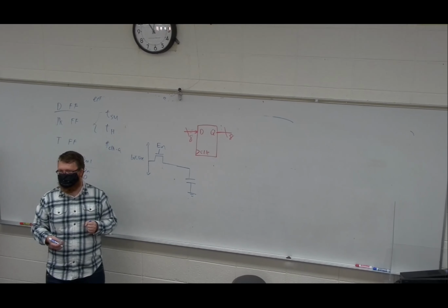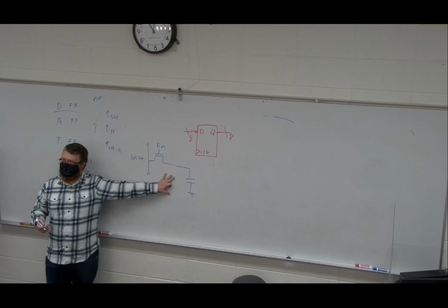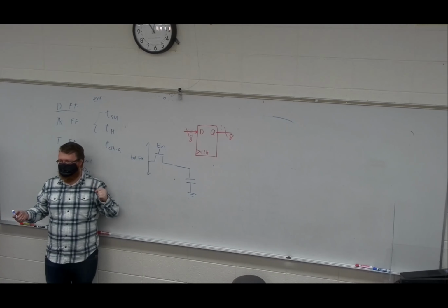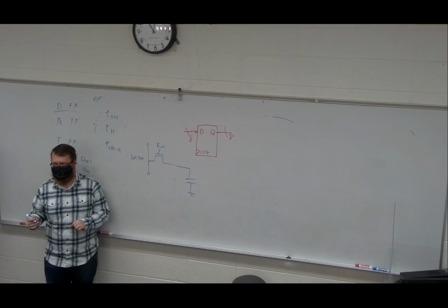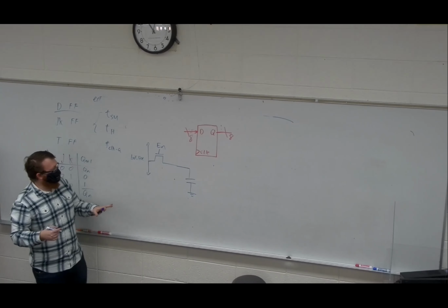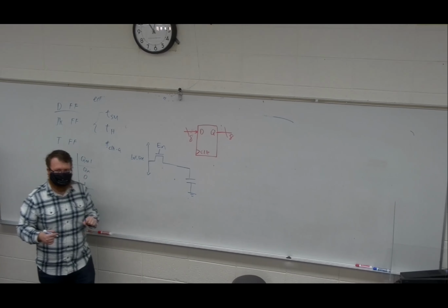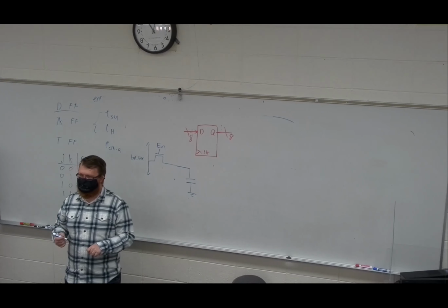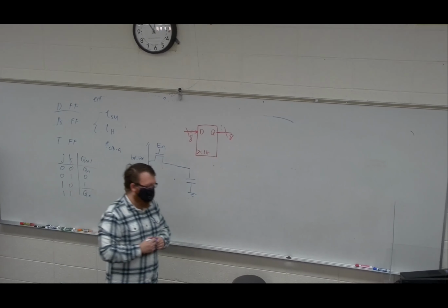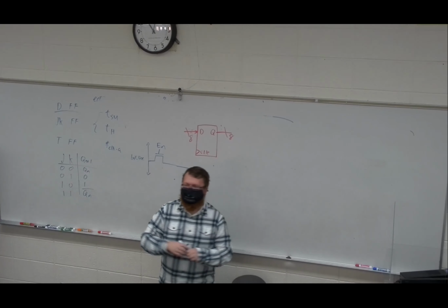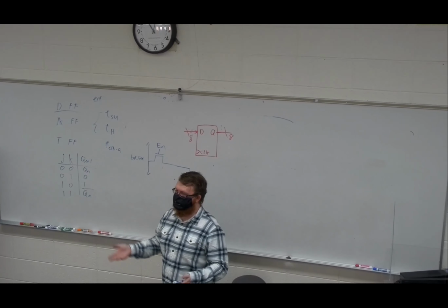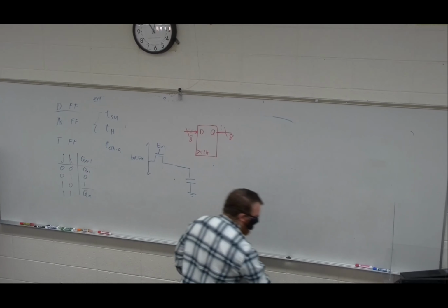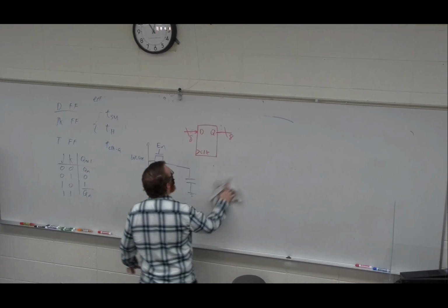That makes sense, right? This is one of the simplest ways that you could store a bit. One of the challenges is that it's very fleeting. If you turn the power off on the device, it just goes away after a fairly short amount of time. So this is one implementation of what we would call DRAM, dynamic RAM. We can make it better and have what's called SRAM. It gets more expensive because it takes more devices, but is useful. I'll erase this one.